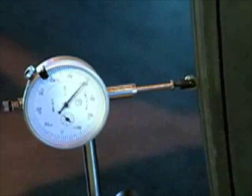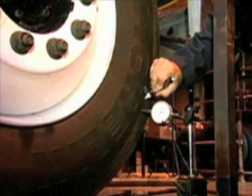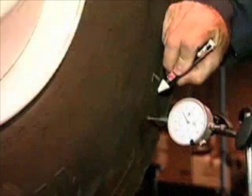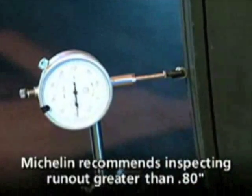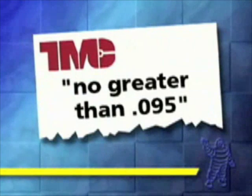This difference is your lateral runout. Mark the position of the high and low reading on the sidewall of the tire. We will mark it as HS and LS. This stands for high sidewall and low sidewall. Any lateral runout found greater than 80 thousandths of an inch needs to be further inspected. TMC currently recommends no greater than 95 thousandths of an inch.